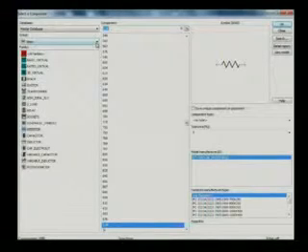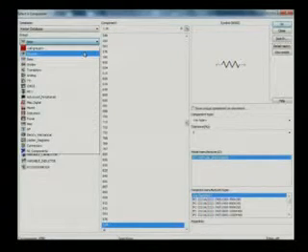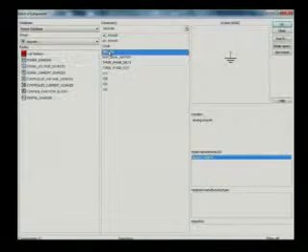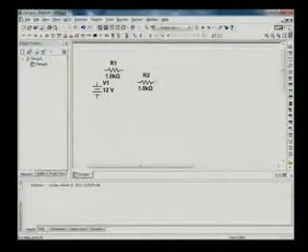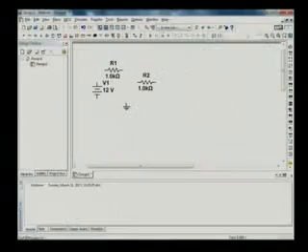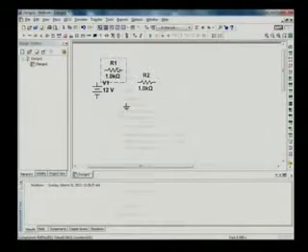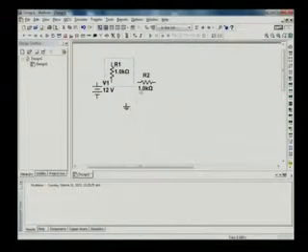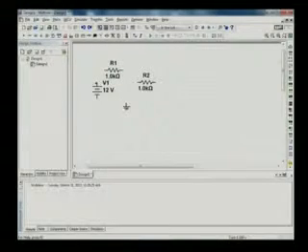Now we want to have the ground connection also. So we will go to sources, and from there the ground connection is there, so we select OK. You will get the ground also, then close it. Suppose I want to rotate this resistance, that provision is there: just right click and you can rotate 90 degrees clockwise, so it will look like this. So now we have a circuit. I'm just connecting it.